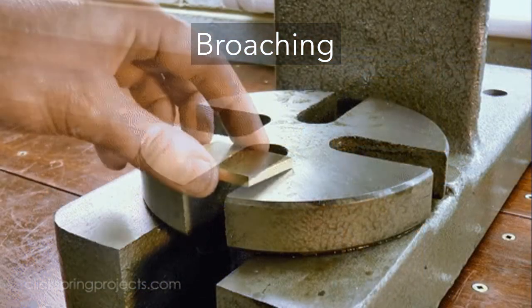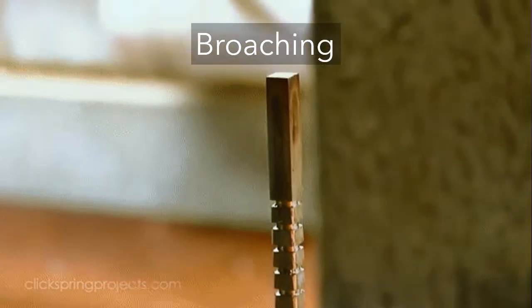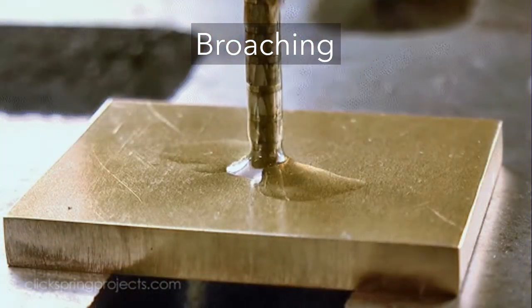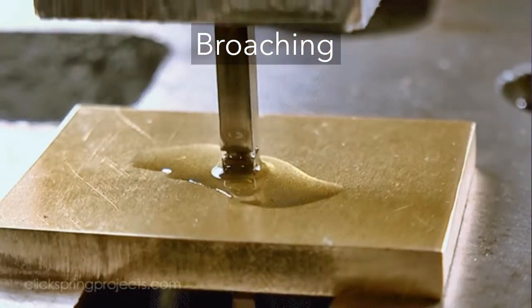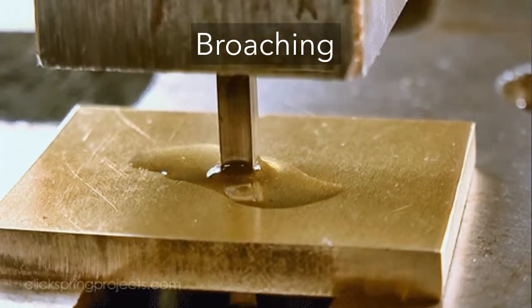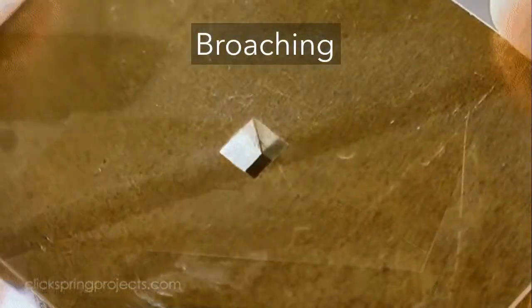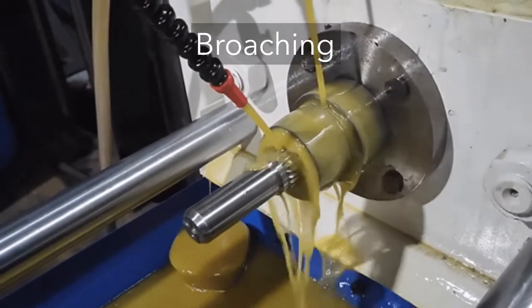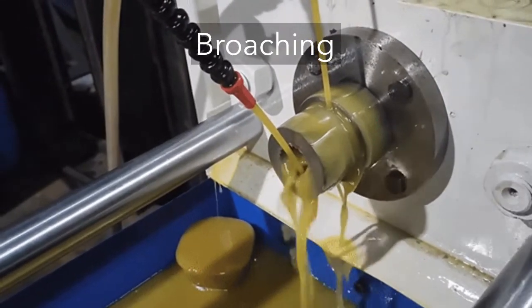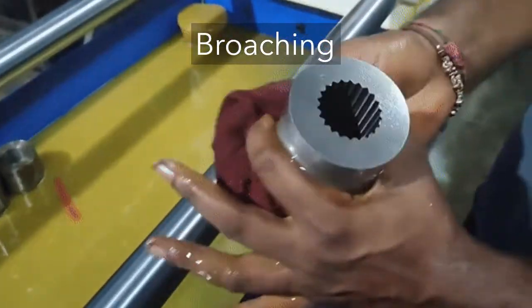Broaching is performed using a multiple-tooth cutting tool by moving the tool linearly relative to the work in the direction of the tool axis. The machine tool is called the broaching machine, and the cutting tool is called the broach. Broaching is a highly productive method of machining, and the advantages are good surface finish, close tolerances, and the variety of work shapes possible.